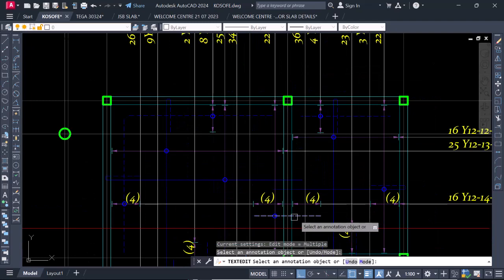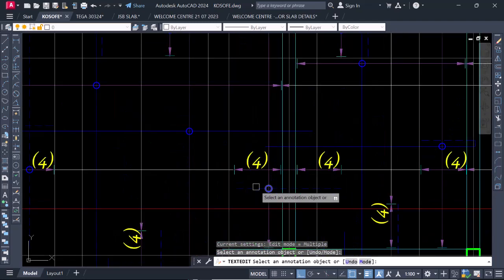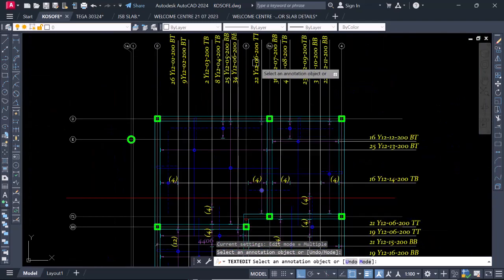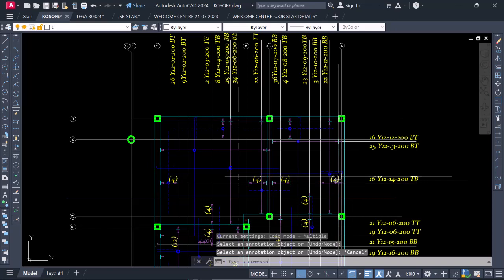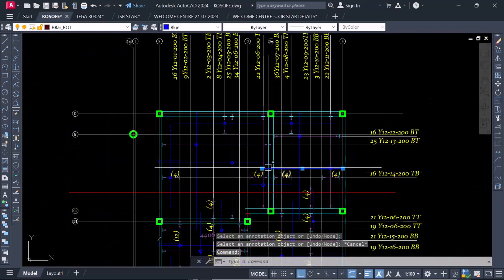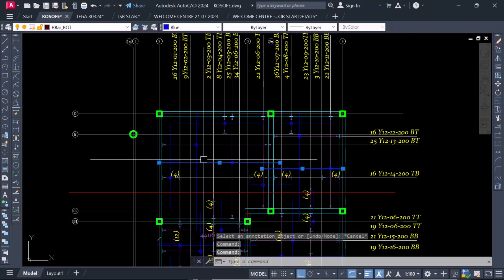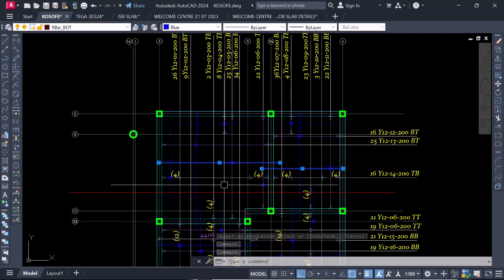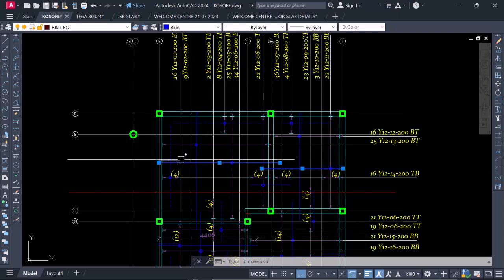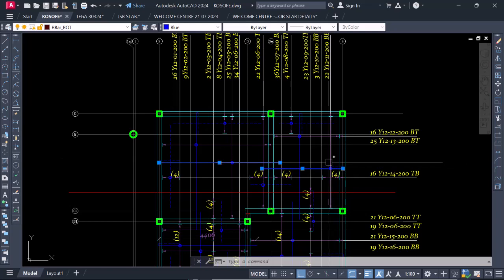This is our reinforcement we are looking at, all right? So the reinforcement trace is 06, all right? This returning here will take the same label as this because we use the same bar to return it, okay? In this our design, we use the same bar to return. So we all name it 11. And here too, we use the same bar to return our top bar and we'll call it 5. So this return up here will be 5 and this return up here will be 5.